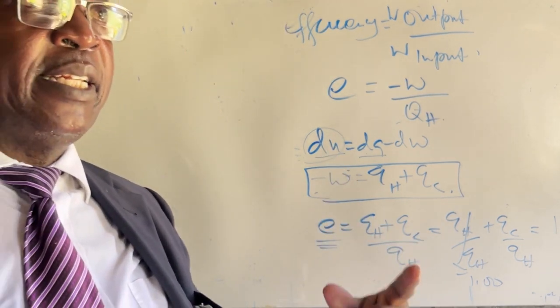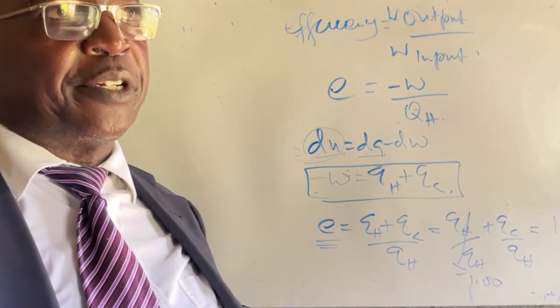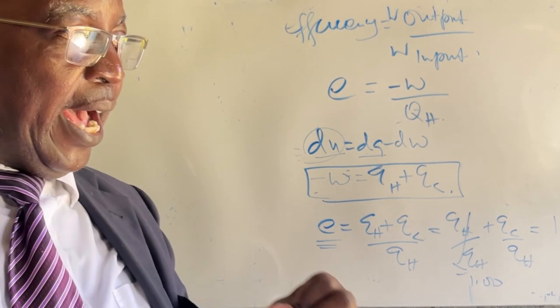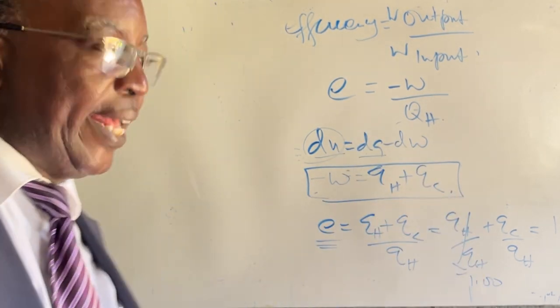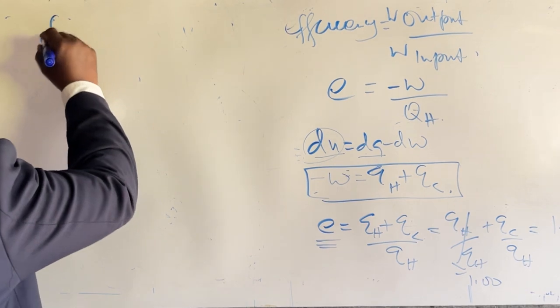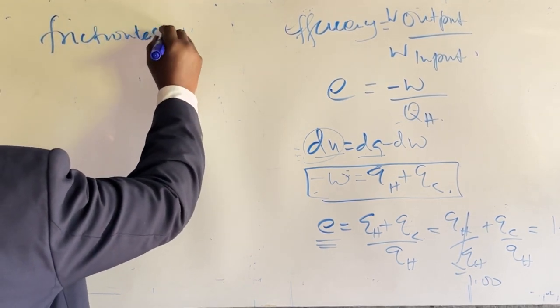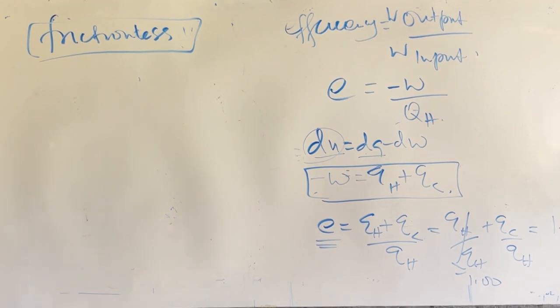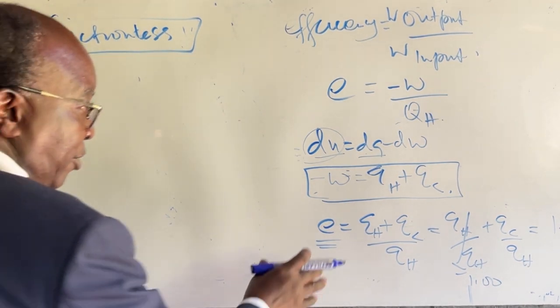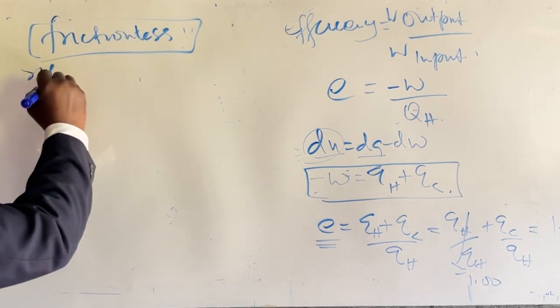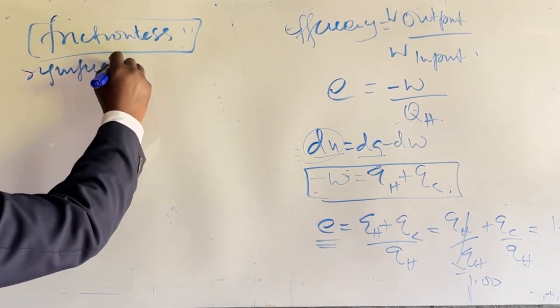We had said that it is rigid, so it's not collapsible, so that we don't have volume changes. And we also said it is frictionless. That is where the problem is. Getting a frictionless process is a nightmare. So there will be frictional effects, which, because the amount of work done is normally very small, will significantly affect the amount of work.